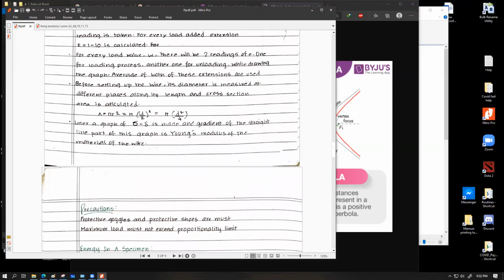along the entire length. But think logically, the wires are made with some industrial process. Having an exact diameter would mean you'd have the exact same number of atoms in every cross section. But manufacturing this precisely is not possible. That's why we are going to preferably measure the diameter in multiple different locations, let's say 4 or 5 locations, and then take the average to get an average value of the diameter.